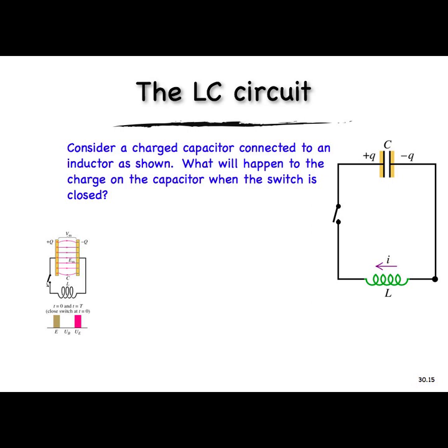Multiply both sides by I naught, and I get an expression for the current as a function of time. At time 0, this term is 1, and the initial current is just whatever it started as. But as time increases, this value goes down to 0. It takes a time L over R before it decays to 1 over e of its initial value. But it asymptotically approaches 0, so I get a current that looks like that.